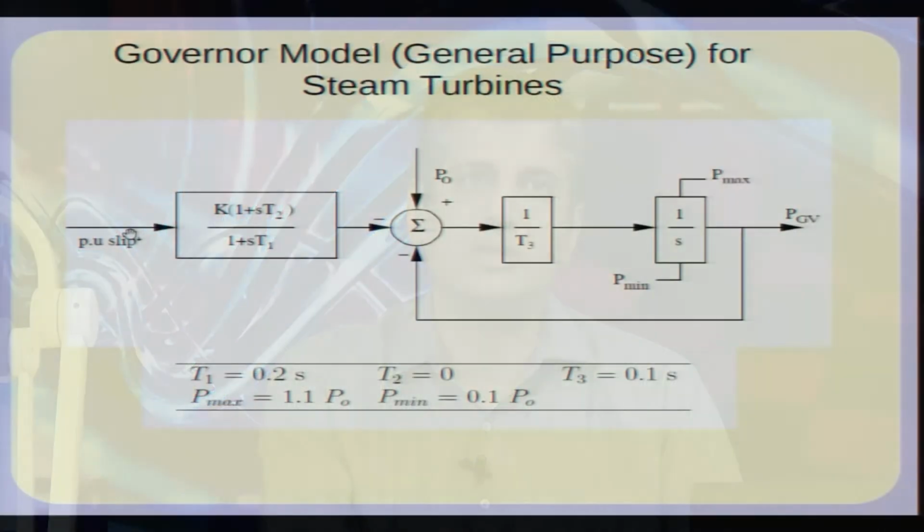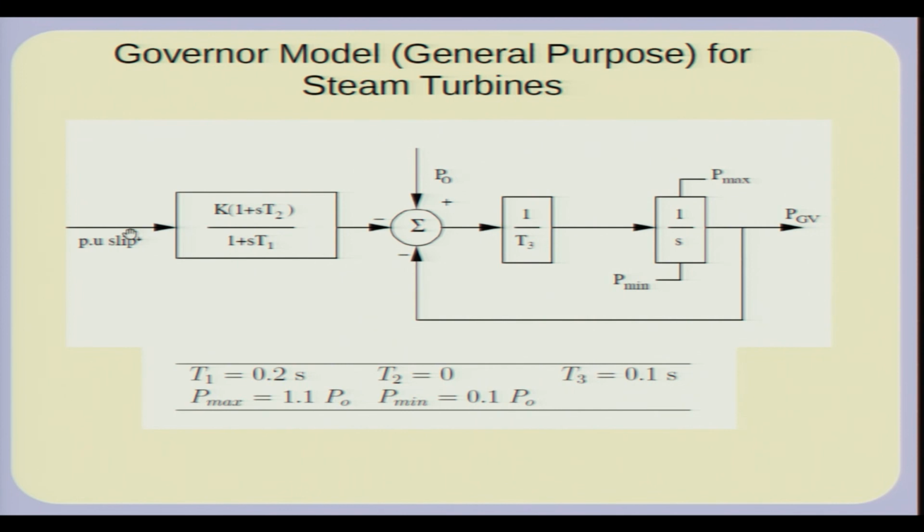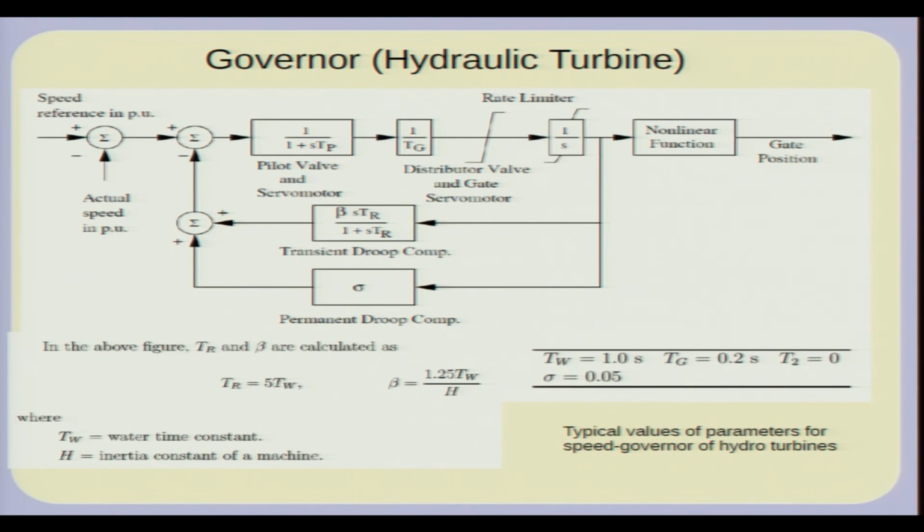However, if you have got a plain synchronous generator, you can actually regulate the speed exactly, just a single synchronous generator connected to a passive load, like for example, in this classroom if you have got a diesel generator supplying this load, you can very well use a proportional integral type controller or an integral type controller, provided it is stable, and regulate the frequency exactly, that is drive the per unit slip. Slip is of course difference frequency, you can drive this to 0. Okay. So, these are some of the concepts which are important.